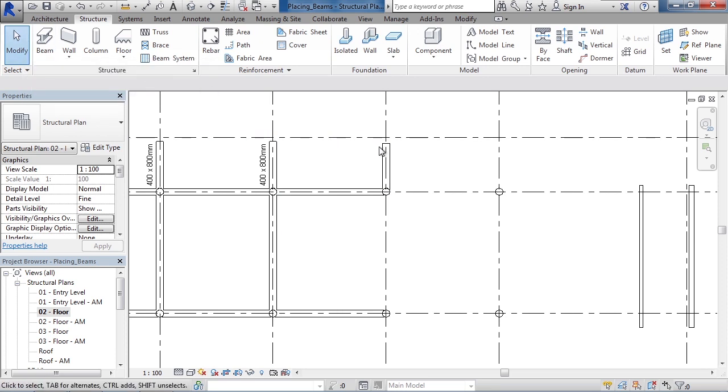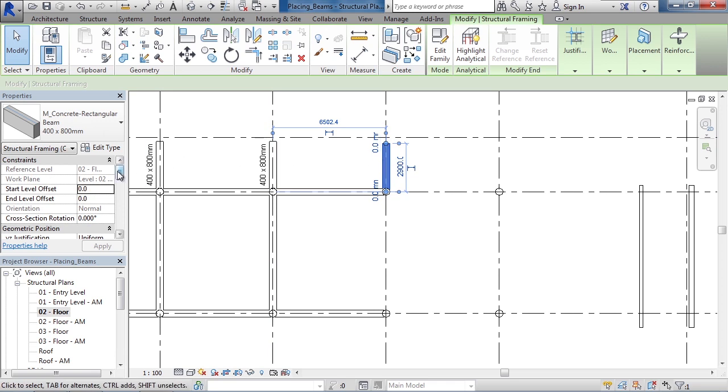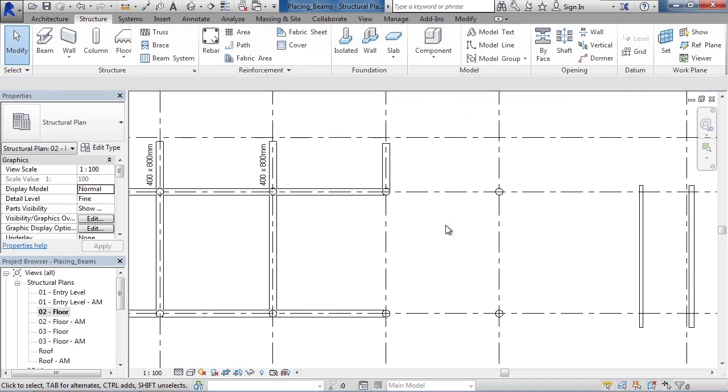To view the information of the beam, click the beam, and then in the property area on the left, I could see the elements of the beam. For example, if there were any offsets, the origin justification, its material class, and other structural criteria or parameters used for this beam. In the upper right, I have a variety of tools as well for my placement, also for the work plane and any justification edits I'd like to make. To deselect, click in the background.